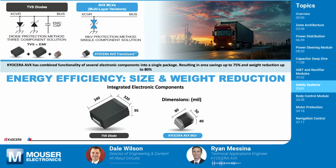And that's where MLVs kind of shine. They go hand in hand with TVS diodes, but what you can see here on these diagrams is your typical orientation on a bus line: two TVS diodes in parallel in alternating directions, and then an EMC cap in parallel with that as well. And with the MLV you can get rid of all three of those parts and just supplement it with one part.